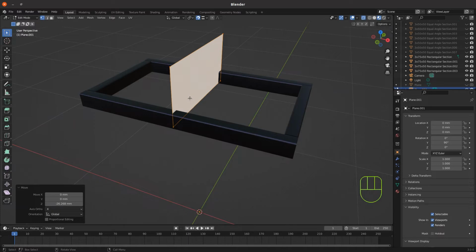So that gives us a plane we can use to cut a thin strip, but it needs some width to it. Depending on what size steel you intend to use for the slats that run across the box section, I'm looking at probably what they use just on a car because I've got plenty of it, so it's about 1.2 mil. So I'm going to put a 2 mil slot in that, and there's lots of different widths of cutting discs for angle irons, ranging from 1 mil up to about 3 mil. So 2 mil would be the obvious size to give you a bit of clearance on 1.2 millimeters to be able to just slot them into the gap.